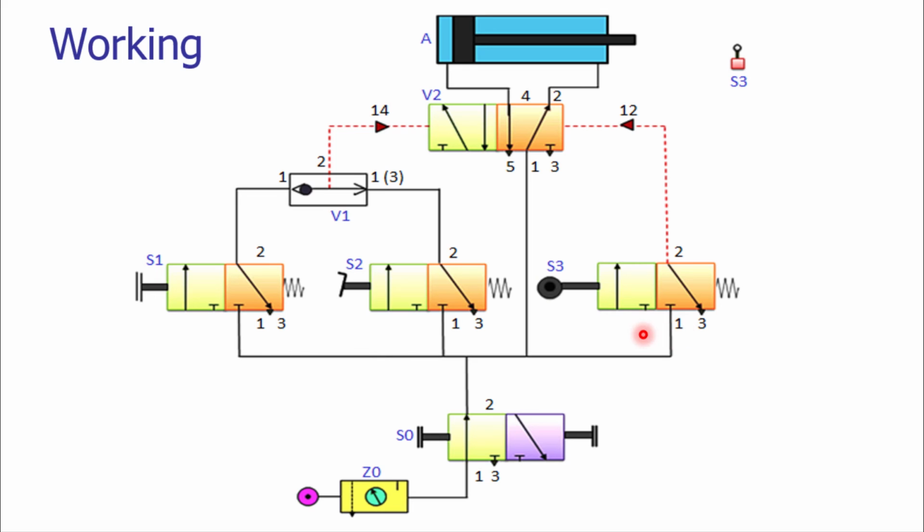So port number 1 will be connected to the input port, and that is giving the pilot pressure for the retraction. That pilot pressure is operating the valve and it is opening up, connecting the input port 1 to the retraction port 2. This is input port 1 and retraction port 2.